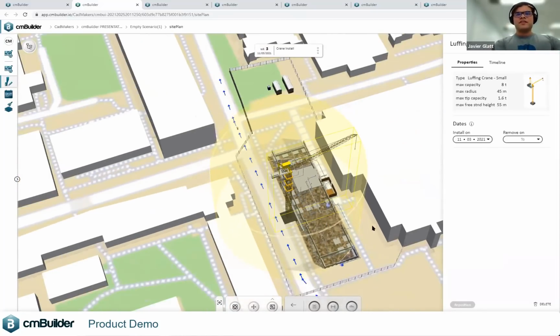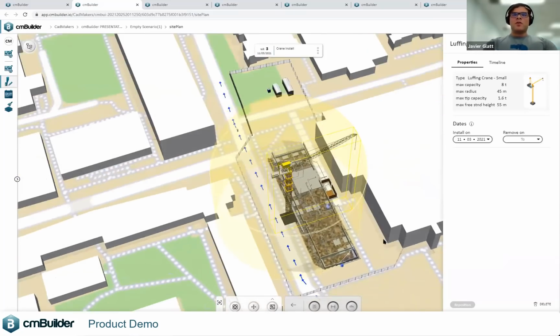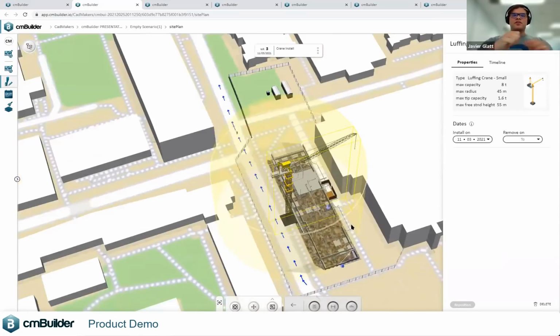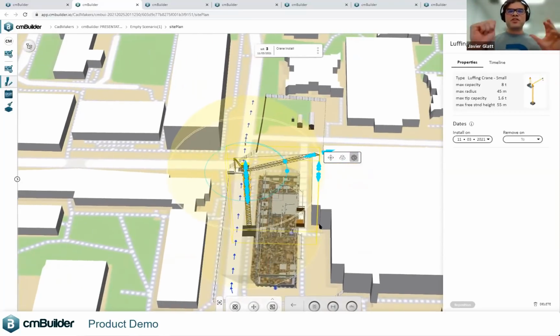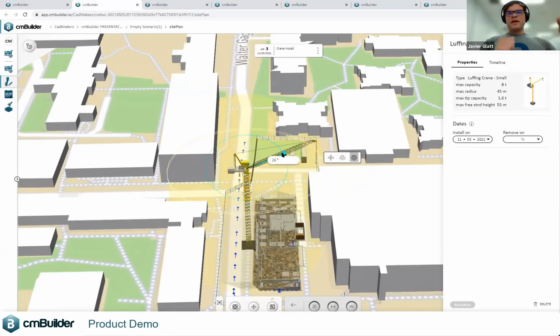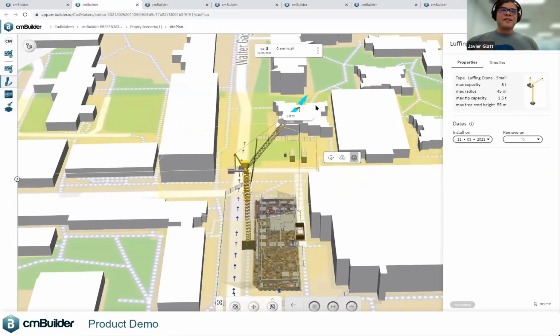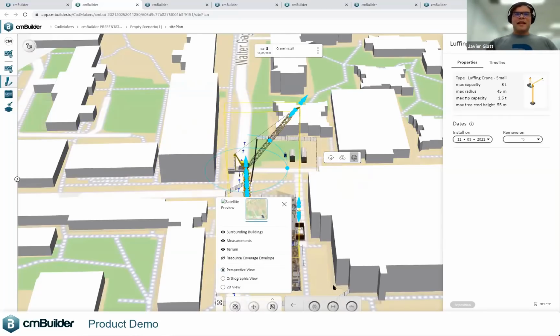And then you can start to move the site. So this is a top-down approach where you actually have a smart parametric crane that you can start to toggle the different parameters. Say, okay, this is the best possible crane. Make sure you can make all the reaches for your laydown area, boneyard, all that kind of stuff, and then place that and visualize if it's not going to clash with footings, any issues with sumps or below grade plumbing when you're placing your crane pad, for example.